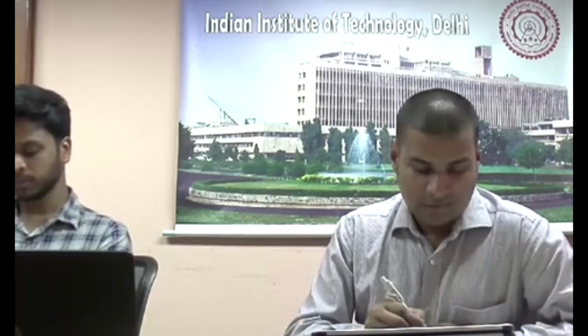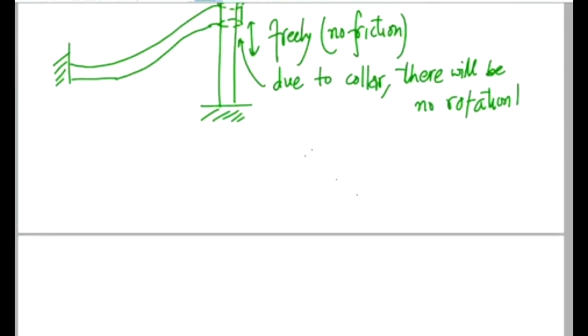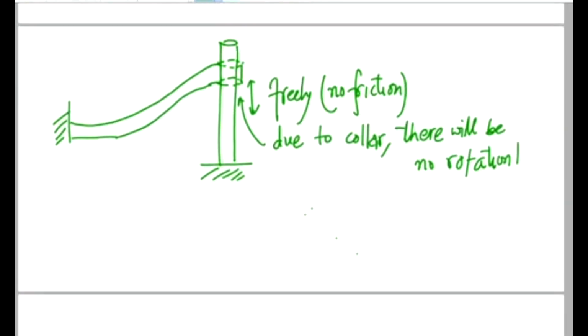So can you think of solving this beam problem, let's say using Timoshenko beam theory? So we'll first write down the equations of Timoshenko beam theory. So that's EI d theta by dx is equal to bending moment, and then dy by dx minus theta is equal to shear force V over kGA.